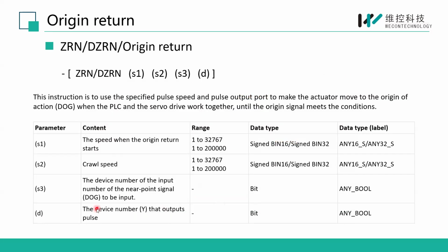About this instruction, only a Y device with the positioning parameter can be specified. After the dog signal is connected for this instruction, the pulse stops immediately, and the pulse frequency can be modified while the PLC is running.